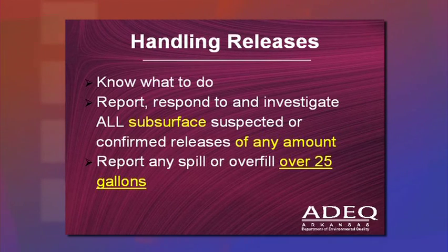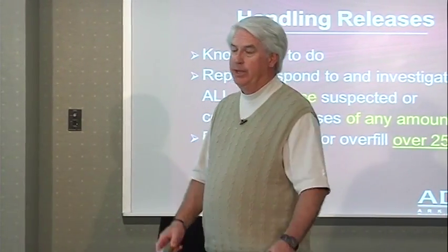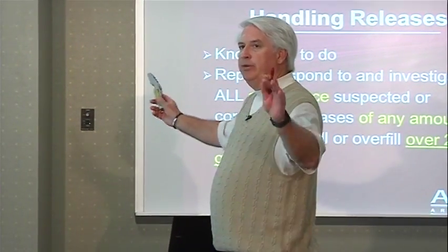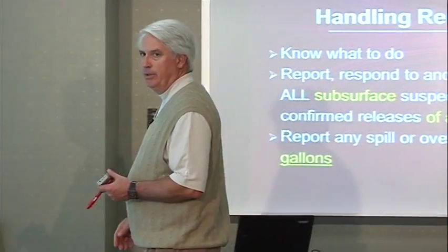You have to report, respond to, and investigate all subsurface suspected or confirmed releases of any amount. Any amount. When you see this on the test, it's going to look like that for sure is the wrong answer. If it's subsurface, how are you going to know how much you've released? You're not going to know. So any subsurface release of any amount.